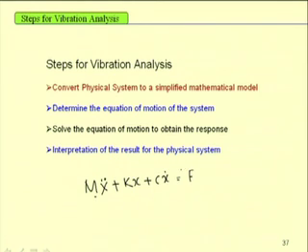So, f is a vector and x is a vector. So, in case of a multi degree of freedom system, one has to solve this. If this is an n degree of freedom system, for example, one can take a 12-story building. In that case one can write this M matrix as a 12 by 12 matrix. Similarly, the stiffness and damping matrices can be written with 12 by 12 elements, and the force F vector will contain 12 components.